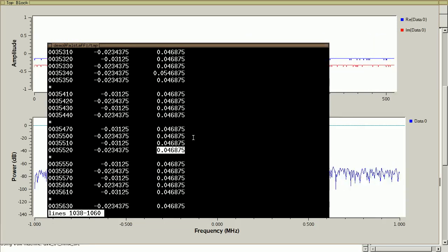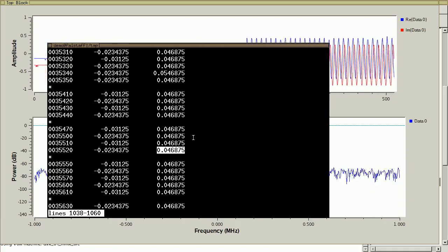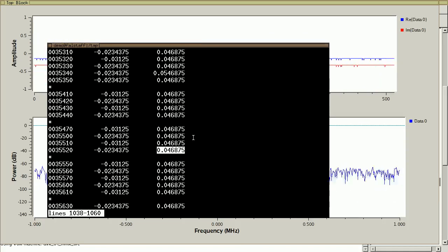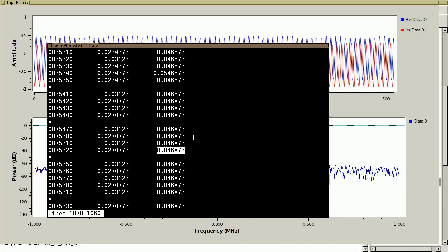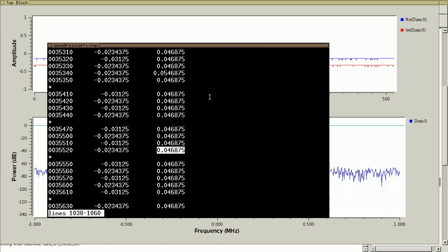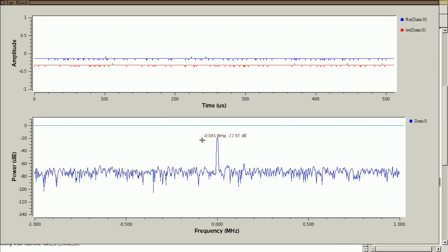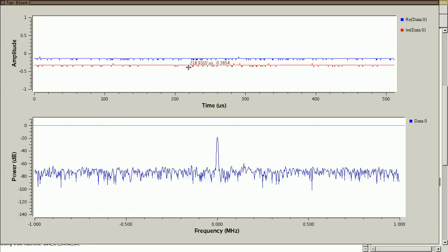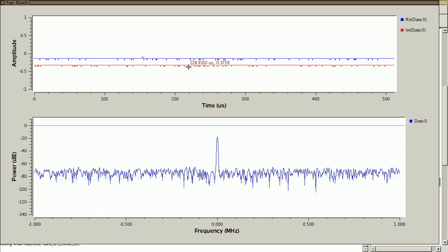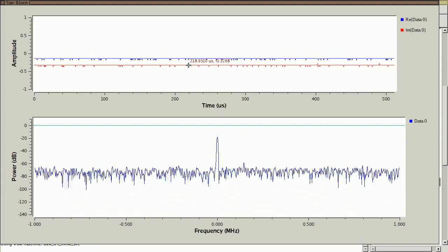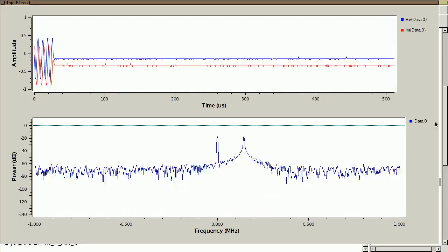And if we have, let's say, only 4 different values being used, then that means we're really only using 2 bits of our dynamic range. We have 8-bit samples, but the high 6 bits are always set to 0. So we're not using very much of our dynamic range. We can use more of our dynamic range when we transmit this file if we multiply it like we are here. And this is a way that we can amplify our signal in the digital domain before converting it to the analog domain.